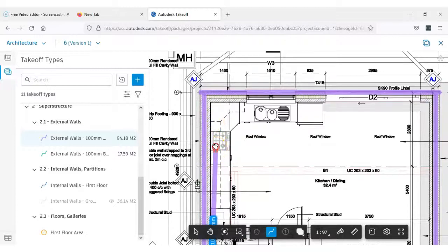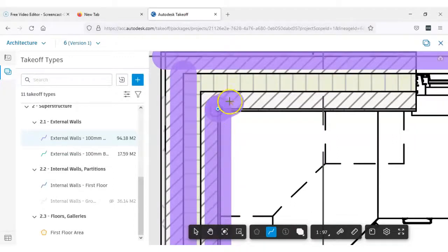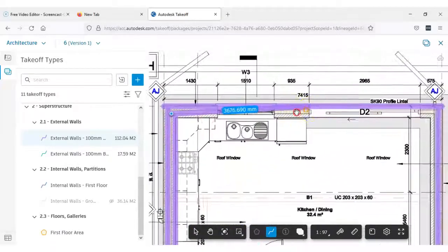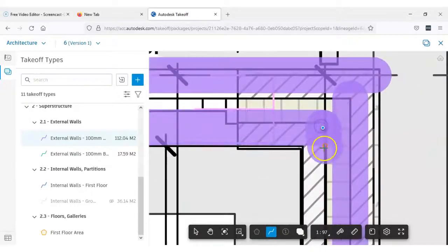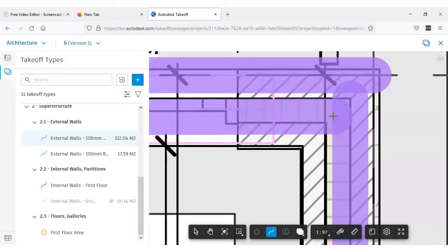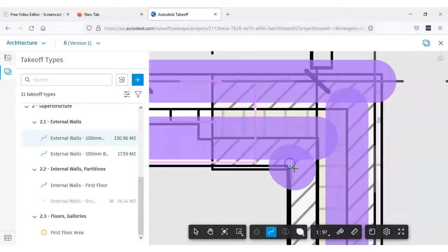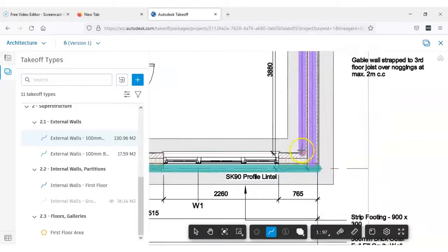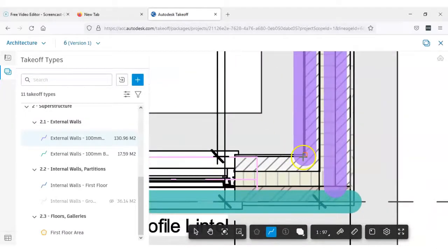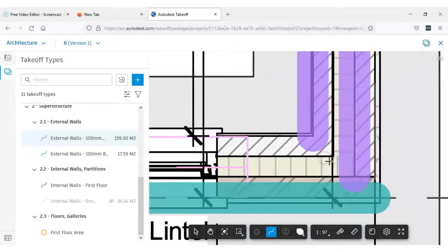Now remember, you can go backspace. So I'm going on the inside face here first. Click, and then enter. And then I'm going outside on my internal leaf. There we go. And I'm on the right line. Go to here. Oh, see, I made a mistake there. If I go backspace. There we go. Enter. And then on the inside, clicking. So I'm working my way around this internal leaf. Back down to, say, here. I'd have to zoom in to get the exact item, and then I think this is my last one.